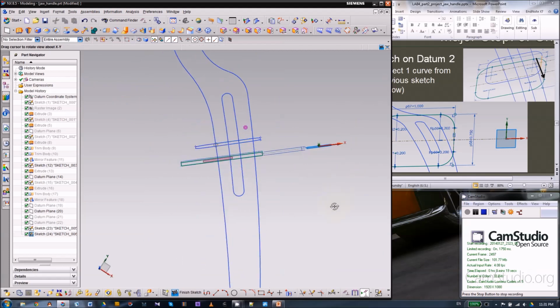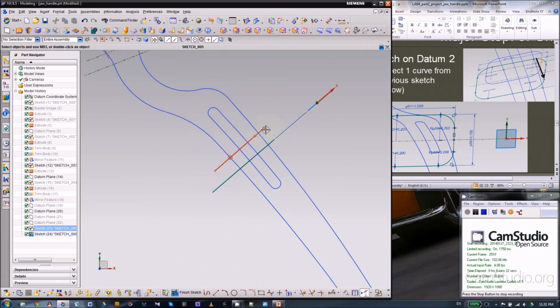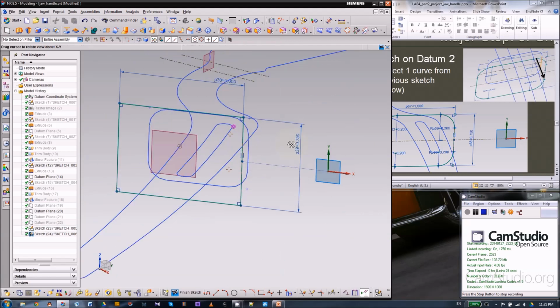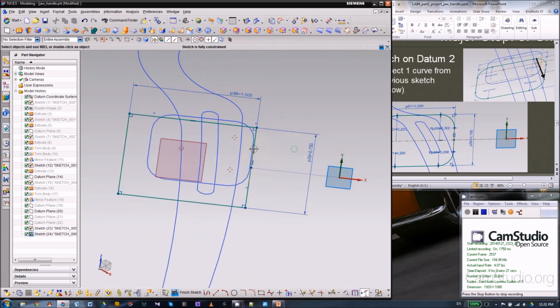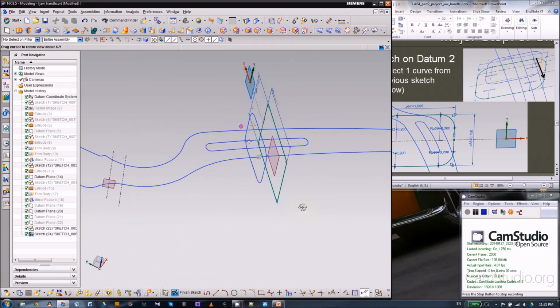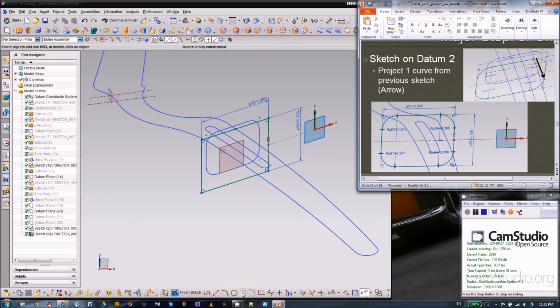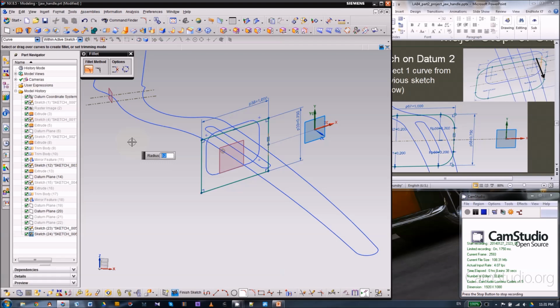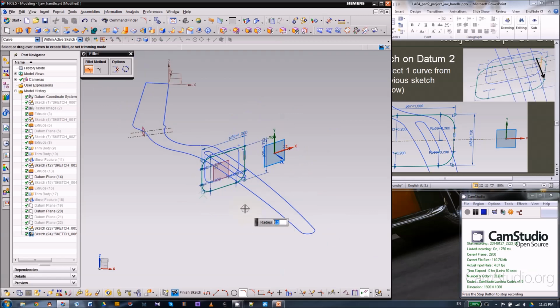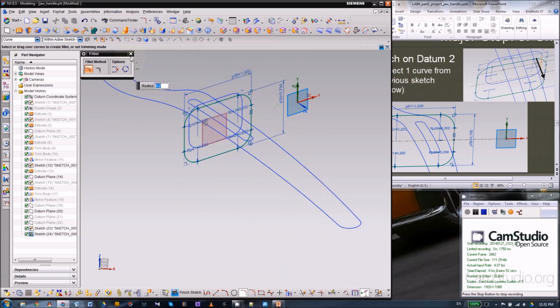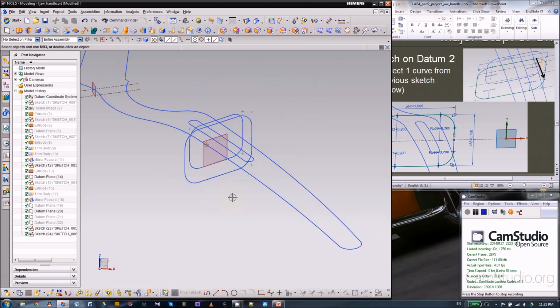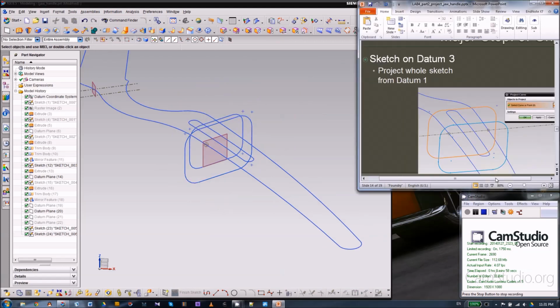So what's that for? If you look at this way, these two lines, they are flush to each other. Okay. Then fillets, 0.2 inch, 4 corners. Control Z, and okay, always better to just click 2 lines for me. Okay, finish sketch. Let's go to the next.